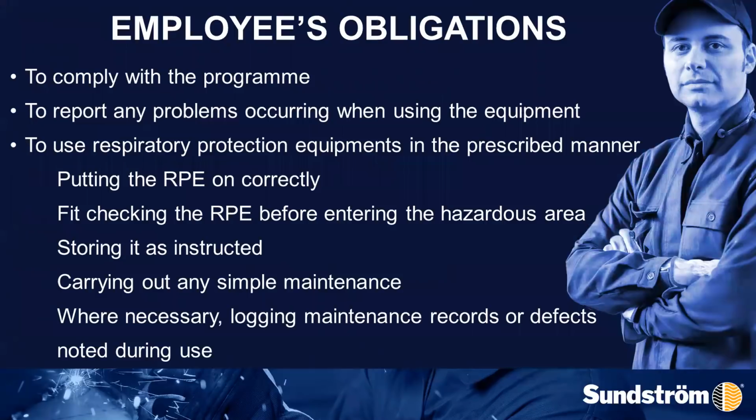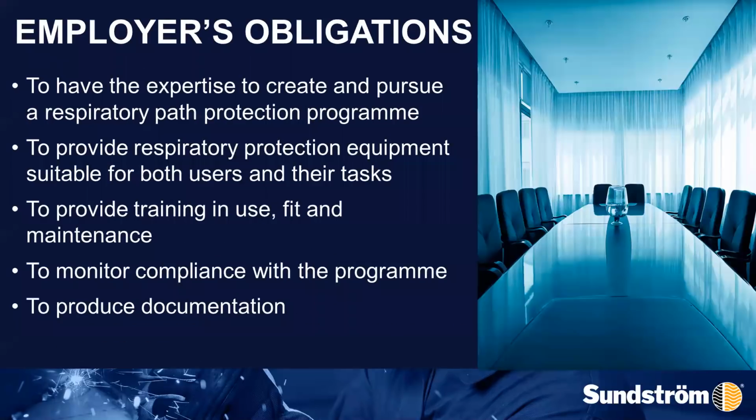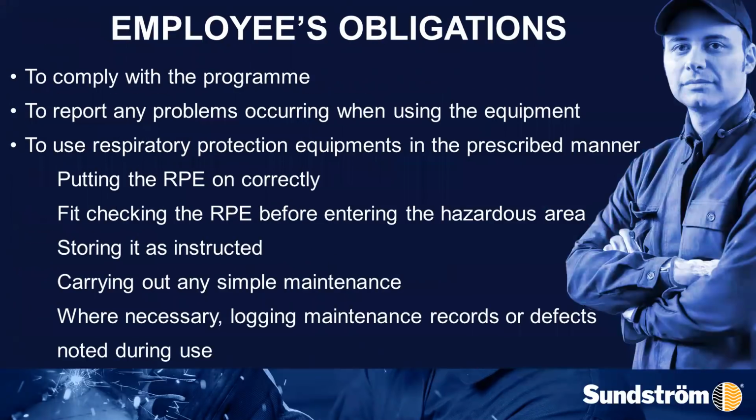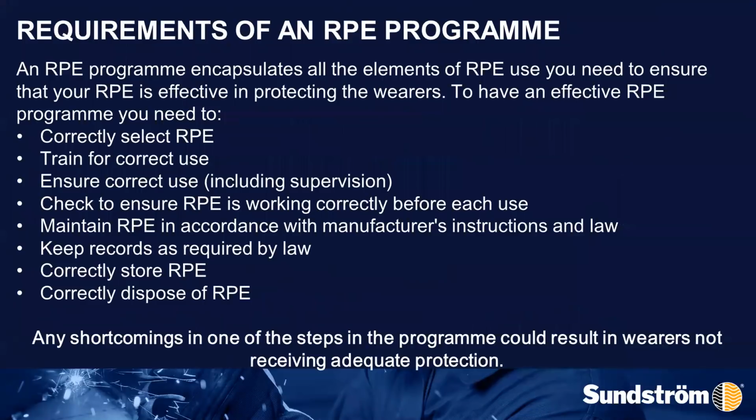The employee also has some obligations, and they are to comply with the program, to report any problems, and then to use the equipment in the manner in which they've been told to, or shown to, or trained to, including putting it on properly, maintaining it, storing it correctly, etc. So the employee's obligations and the employer's obligations really form what is an RPE program, a respiratory protective equipment program.